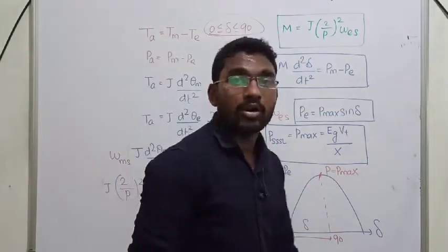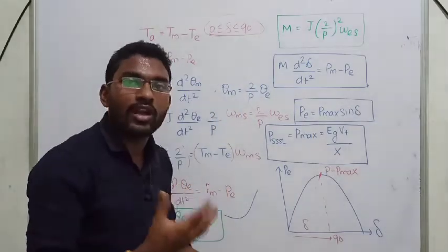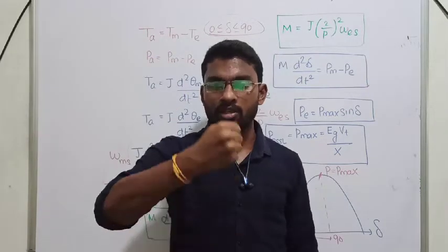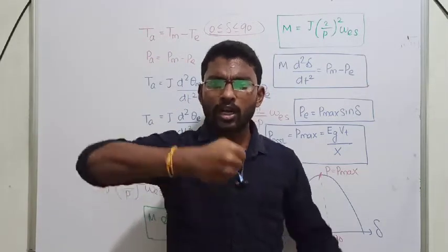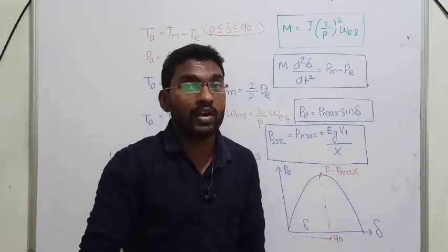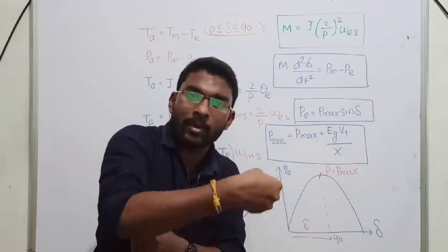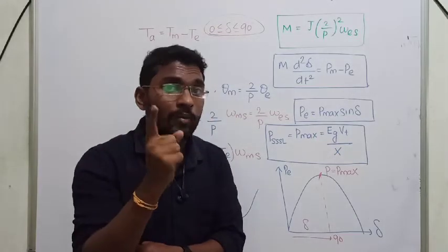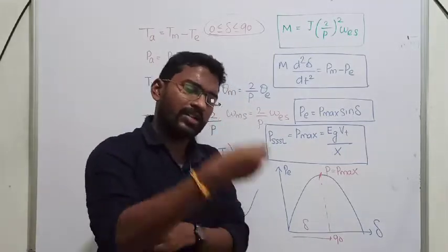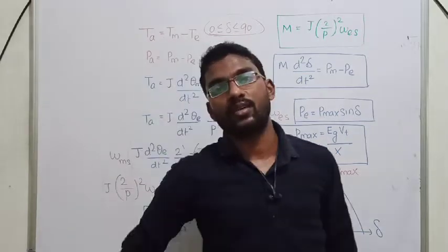Suppose I am talking about transient stability. In transient stability, what will happen? The value of del is changing. You will go beyond 90. Guys, listen. The system is running from 0 to 90 with some small disturbance, but suddenly a large disturbance will be there. Then the rotor will be forced to go beyond 90. The value of del will cross 90, but it won't stay there. It will get back. Because as I told you, during transient, the system will accelerate and decelerate, the swinging slowly decreases, and at last it will become steady state, but the settling point will be less than 90 once again.